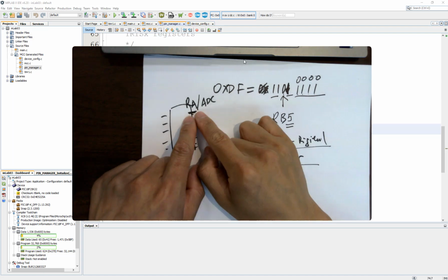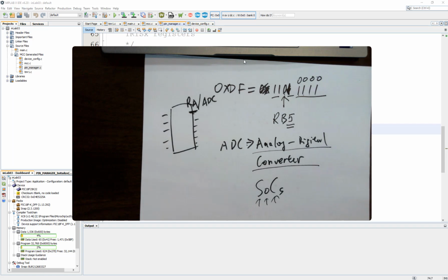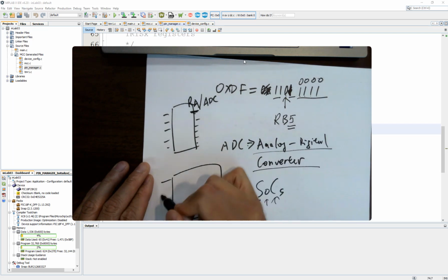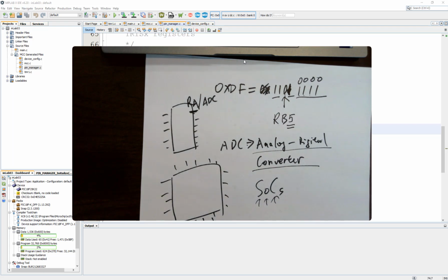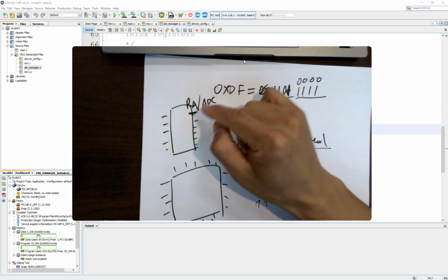If you don't have this multiplexed, you also want the user to be able to use ADC converters. So you would have to generate more pins, which means you need a bigger chip with so many pins on it, which will increase the cost of the chip. So we have a tiny chip with only about 28 pins, so a lot of them have to be multiplexed.